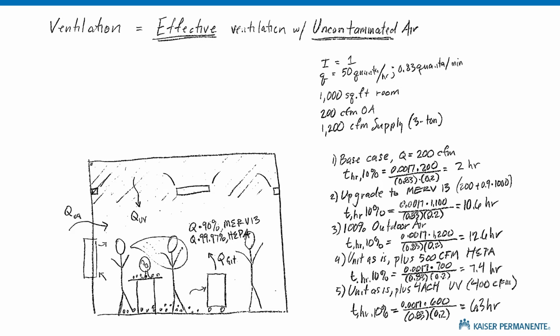On a long-term basis, a 1200 CFM 100% outside air unit is more like 7.5 or 10 ton and not 3 tons. And so changing that is going to be a project that'll be well over $10,000. A HEPA filter unit that you put in the room would be $1,000, maybe less, but those are quite noisy. And then the UV light system here is probably the most expensive. A permanent install would probably cost $25,000, $50,000. Project costs are more once you get it installed and wired and all that.